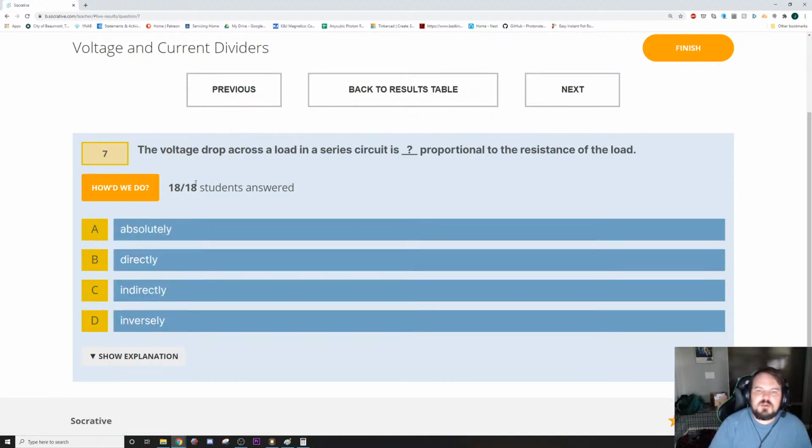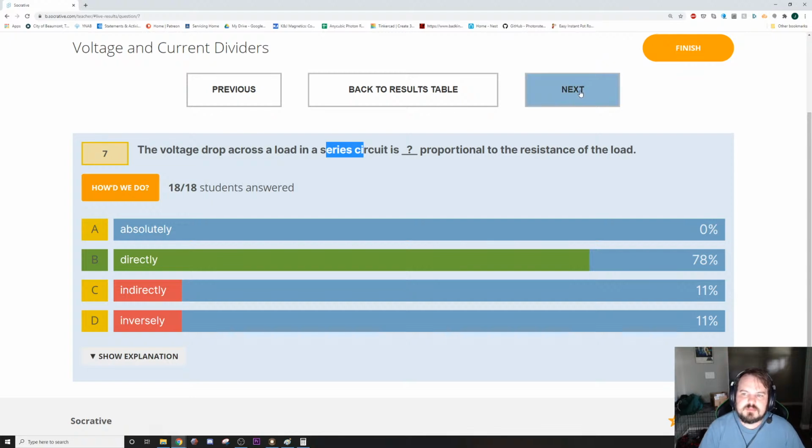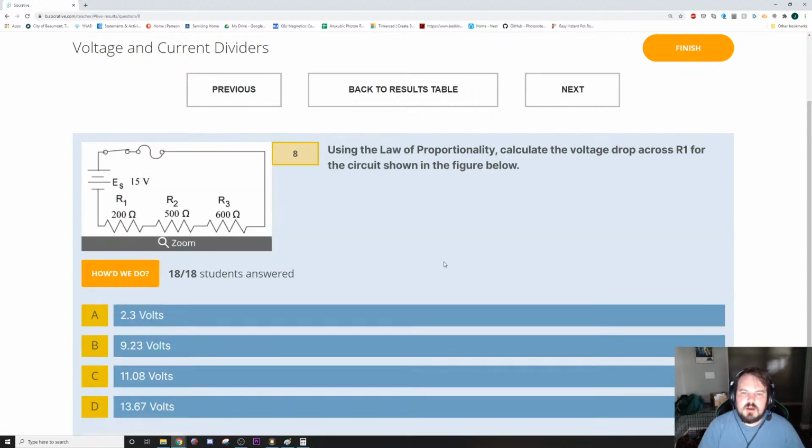Voltage drop across a load in a series circuit is directly proportional to the resistance of the load, just like we saw. It's exactly the same percentage as the resistance of the load. Alright, using law of proportionality, calculate the...